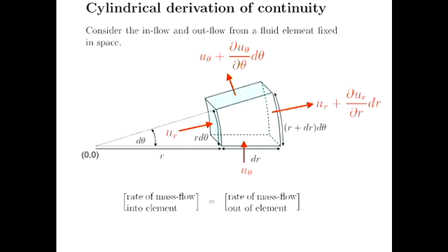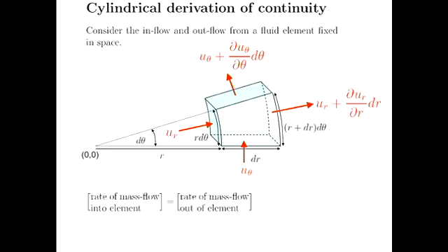So then it's just mass flow, the mass flux, which is a rate of mass flow. So the mass flux into the element must equal the mass flux out, okay? So mass flux in is quite simple. Remember, the mass flux is the volume flux multiplied by the density, all right? And I'm going to keep saying that until one of you gets angry with me, because it's absolutely critical for every topic in this course. All we do throughout this course is apply conservation of mass, conservation of momentum, and for the latter part of this course, we also use conservation of energy. Everything we're doing is based on these conservation equations, all right?